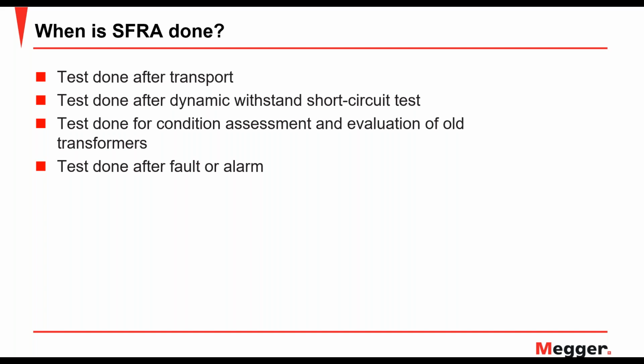The SFRA test, although it's a special test, can be done as part of a maintenance program to do a general condition assessment evaluation on transformers which have been in service for a long time. Also, if a transformer is subjected to a fault, then one way to look for any physical damage to that transformer is by doing an SFRA test.